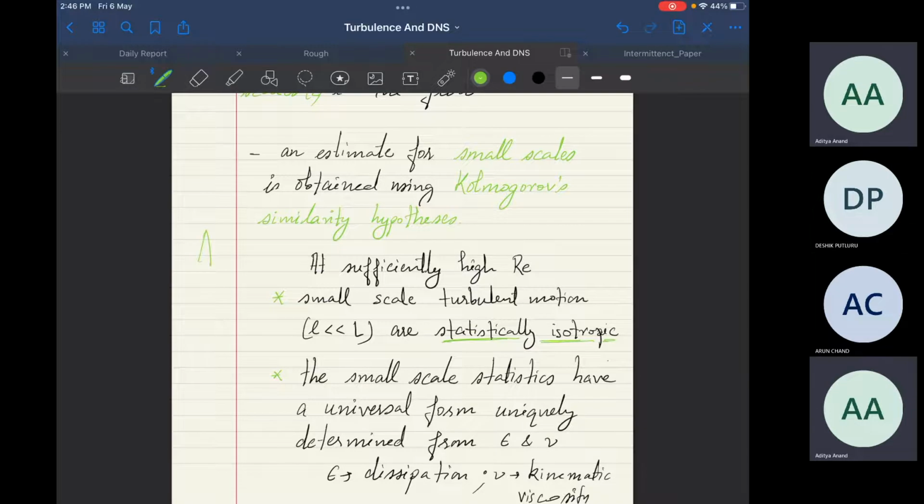So we have a rocket here, and there is an exhaust jet from this rocket. Now there are shear layers present at the edge of this. There is a high velocity here, and the ambient is stationary here. So there are shear layers present at this interface and this interface. As a result, we see large eddying motions, also known as coherent structures. These are the large eddies that are present in the flow.